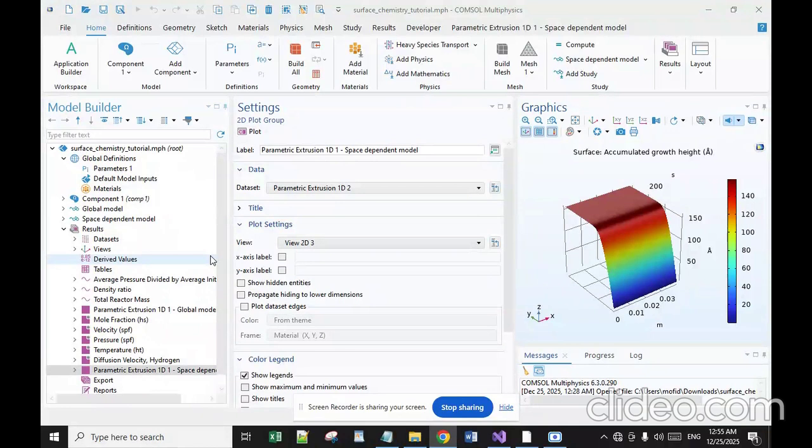An alternative process uses a hydrogen-based solution. The hydrogen reduces the growth rate, but the temperature is raised to 850 or even 1050 degrees centigrade to compensate. Polysilicon may be grown directly with doping if gases such as phosphine, arsine, or diborane are added to the CVD chamber. Diborane increases the growth rate, but arsine and phosphine decrease it.